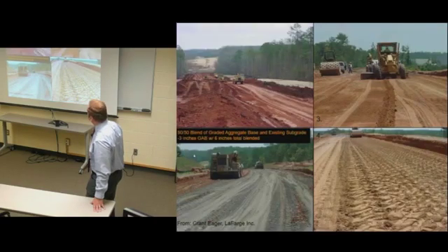There are some construction pictures of this road. In some cases, the subgrade conditions were not that favorable. They had to do subgrade improvement by blending with aggregate. This is still the subgrade, because they had to achieve the SSV value, subgrade soil support value, of 5, right?